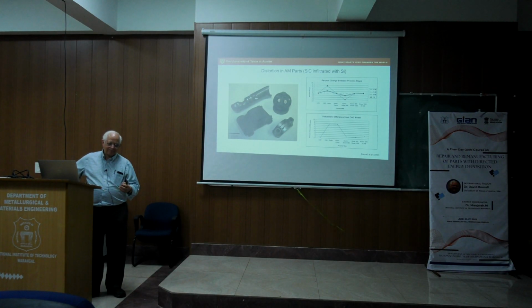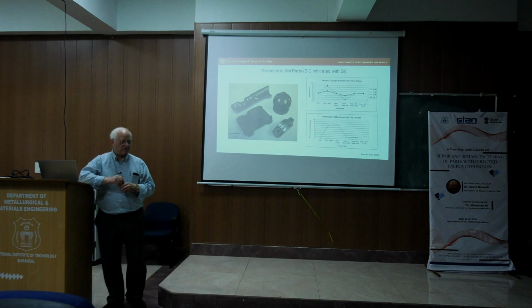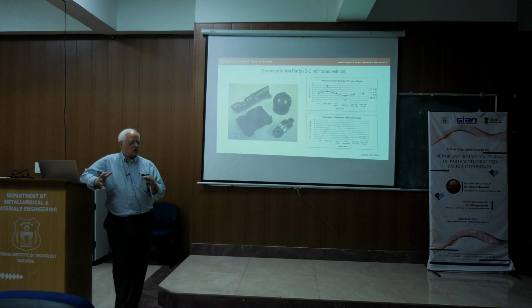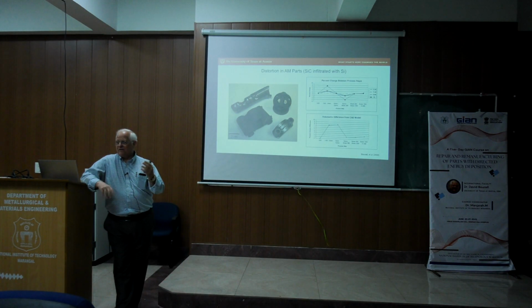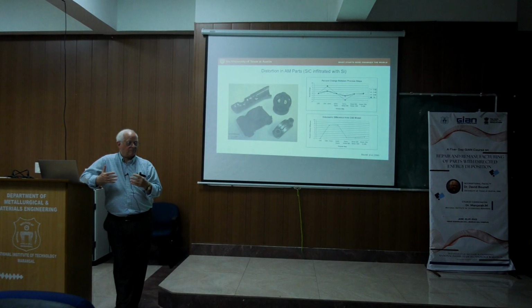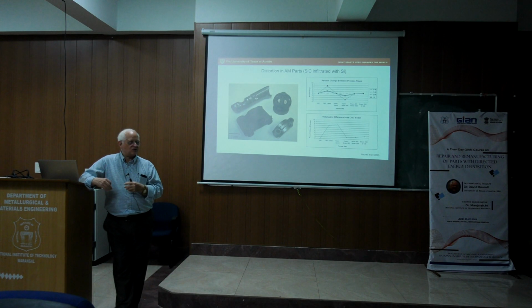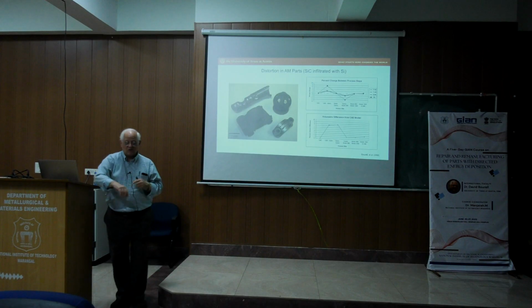Having said that, for a lot of additive manufacturing metals, the surface finish is often not acceptable for a final part, so the critical surface is often machined. And if that's the case, this type of distortion is really not that big a deal because you machine back to an acceptable state. The only issue would be if there's enough shrinkage that you have lost all of your excess material to do the machining. That sort of thing can happen.